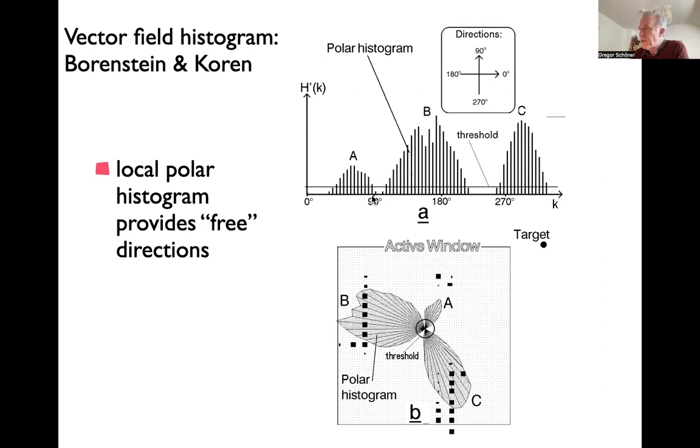And so from that location, as you look into 360 degrees around the vehicle, there are directions in which there were a lot of counts of surface detection and directions in which there are few counts. So if you just select directions in which there are few such counts, then you're going in a direction that is free, that is unencumbered. And of course, the range depends on the sensor, right? The sensor will only look this far. So when there's some stuff very far, that will not enter. So the distance dependence comes through indirectly through the sensor characteristics.